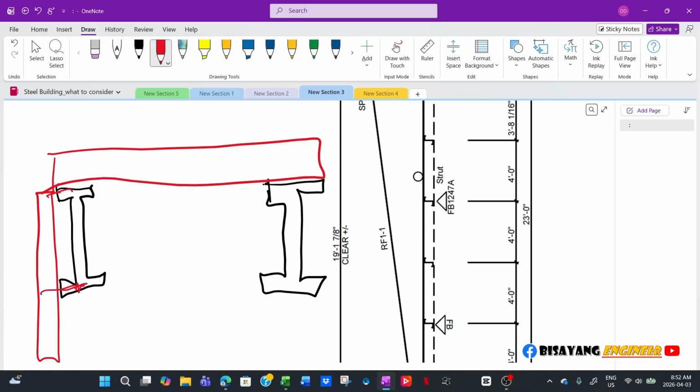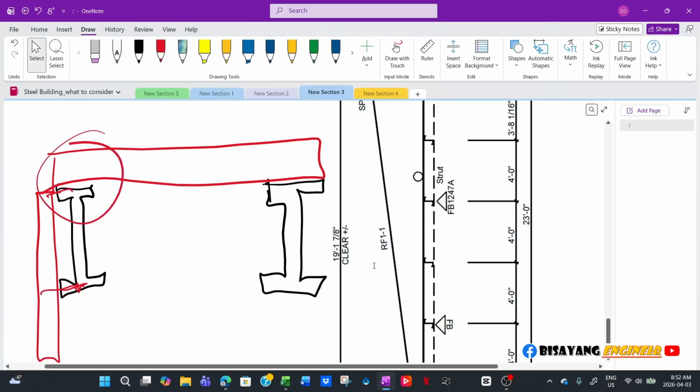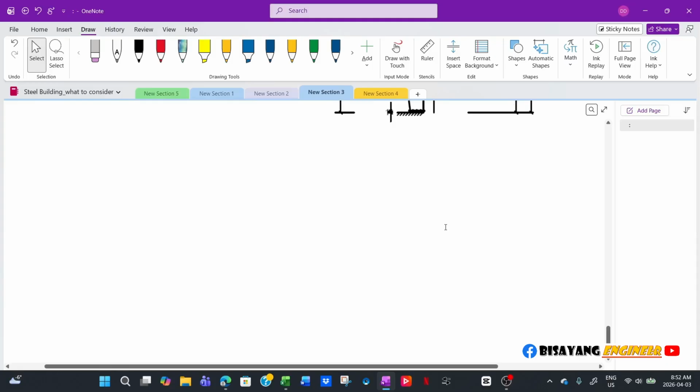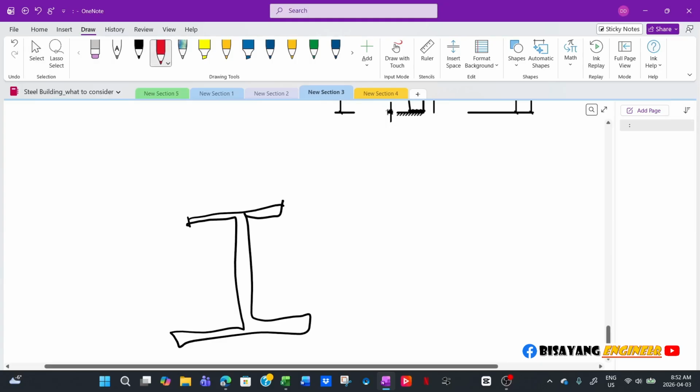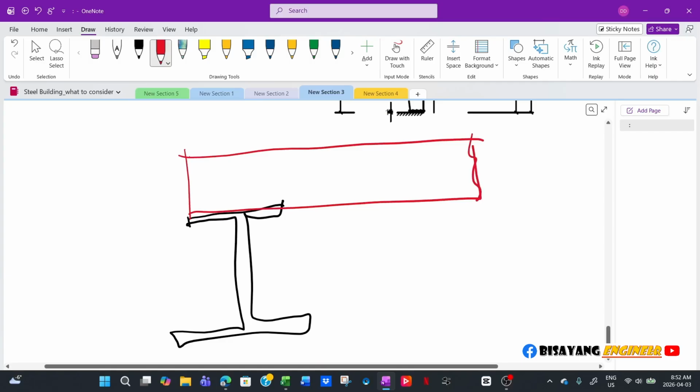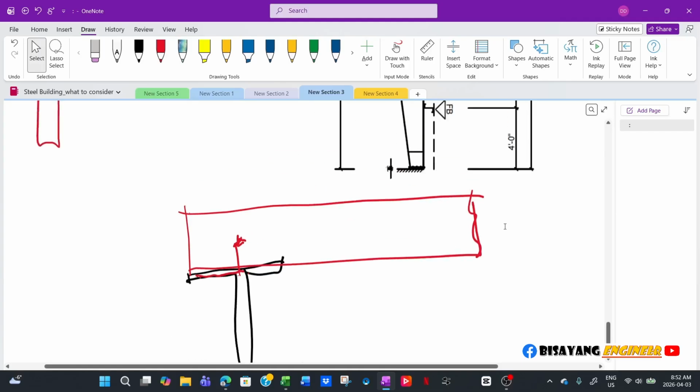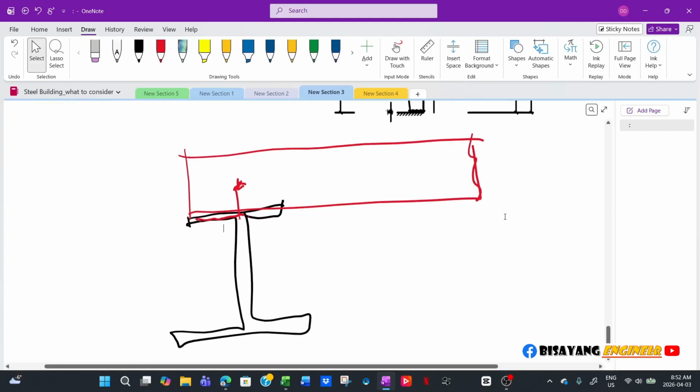Now, if you notice at this joint, you will have the frame, and then you have the four links like that. So the load is from this frame to the four links, and then transfer that to the other frames, and then back to the cross bracing on the roof or down to the cross bracing on your wall.